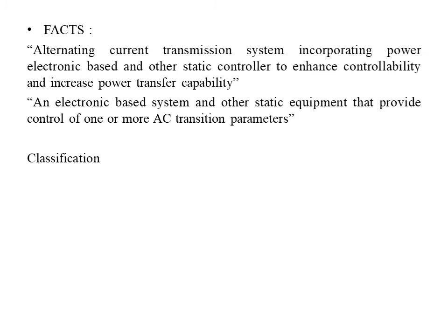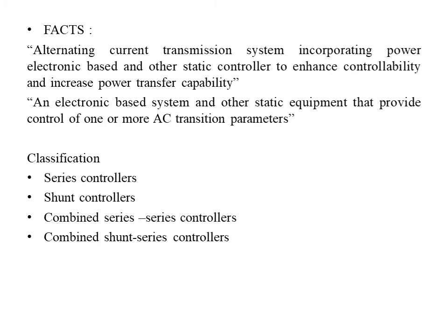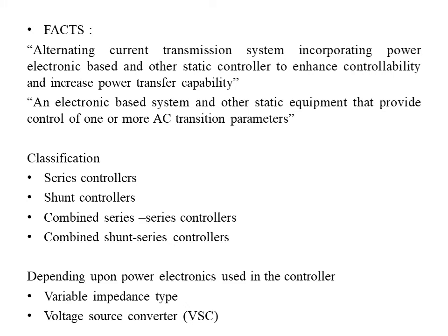Classifications of FACTS are series controller, shunt controller, combined series controller, and combined shunt series controller. Depending upon the power electronics used in the controller, there are variable impedance type and voltage source converter type.